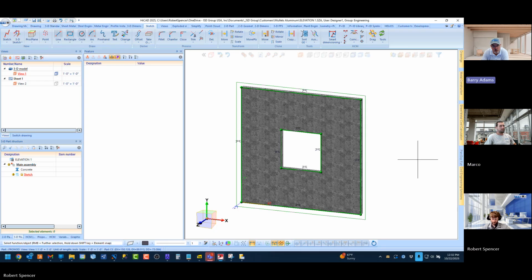But for SolidWorks, that would be convert entities. So it's the same thing. So you're taking an element that's pre-existing, and you're extracting the edges so you can use them in the sketch. Yeah, sounds like a similar function for SolidWorks.